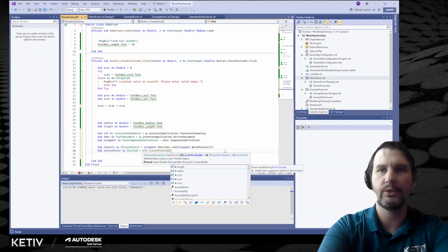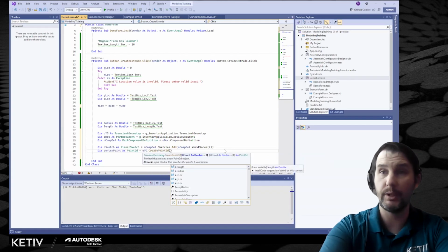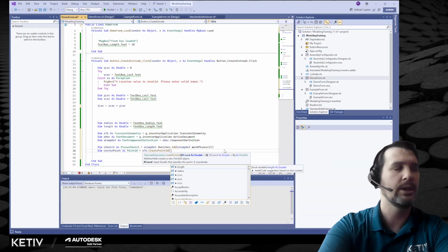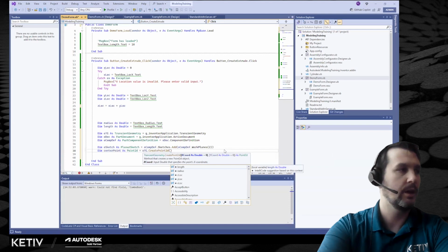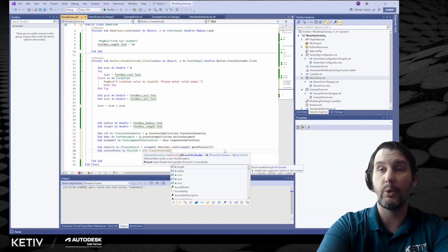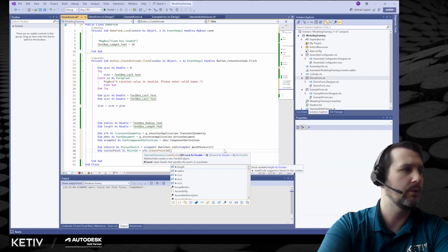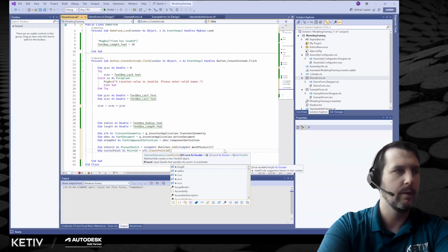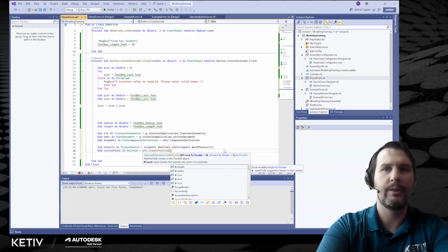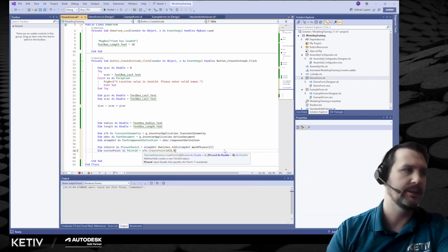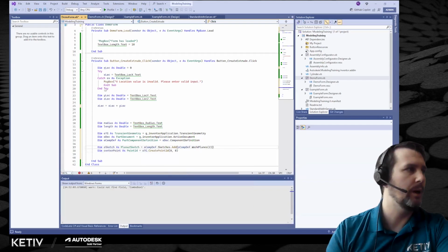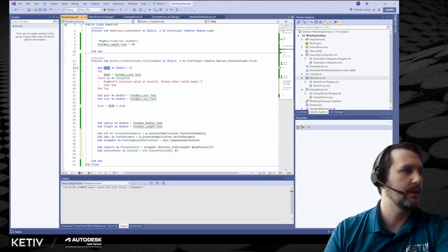And this will allow us to make it's not making a sketch point. So that's one thing that's important to notice here. You're not going to actually see this point as a sketch point in the sketch. You can do that. You can make a point 2D and then make it a sketch point, but currently we don't care about making it a sketch point. But now we can input the user's input into this to define where that is. So I mean, if we do 0, 0 here, it's going to always be 0, 0. But what we really want is our X location and Y location.